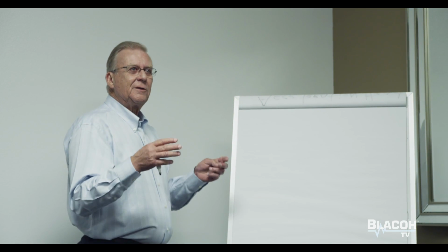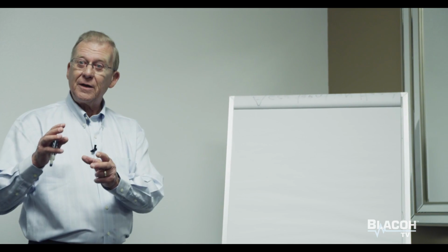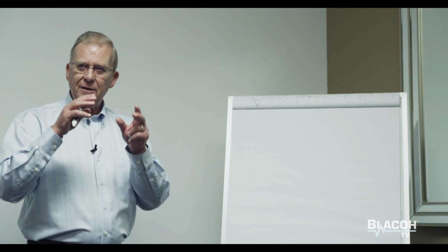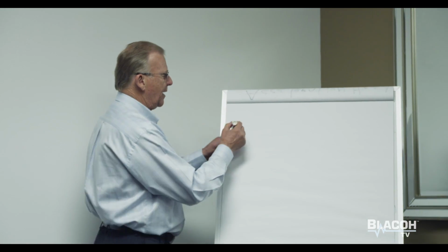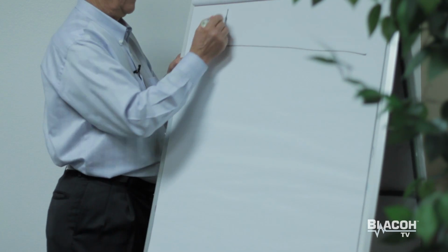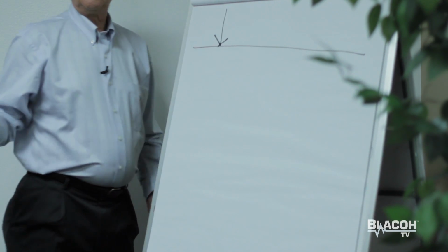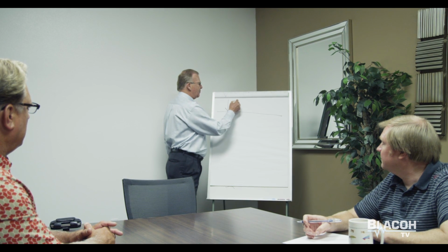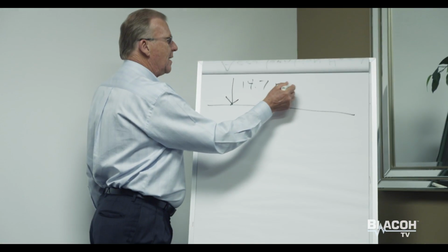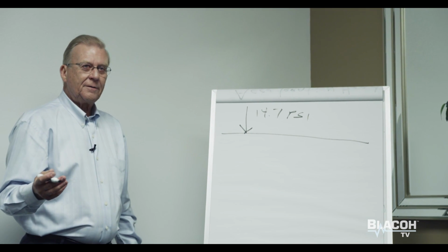Remember, the pump can't do anything until a liquid gets into it, and it applies its energy at that point to discharge it. But up to that point, all we have is what? At sea level, 14.7 psi. Okay?